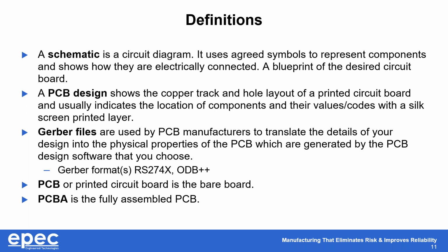These will be included as well. The preferred format for Gerber files is RS-274X or ODB++. Both are good standard Gerber formats and are usually available from whoever does your design and layout.